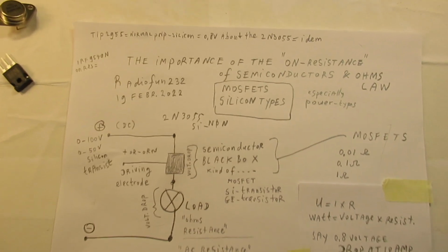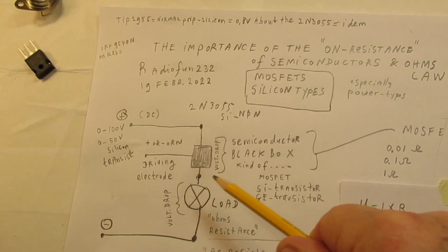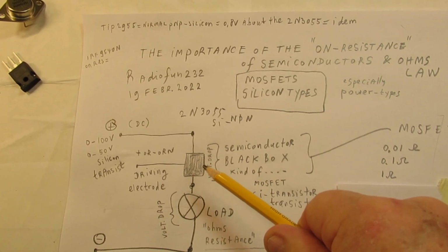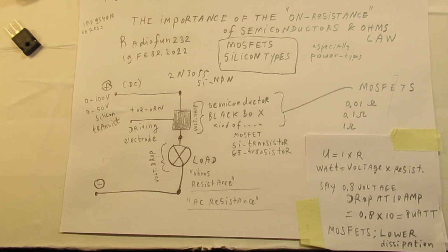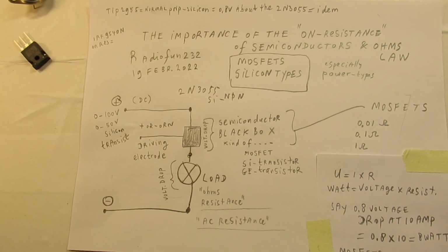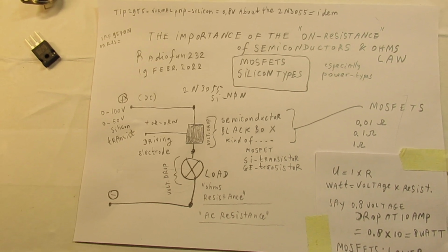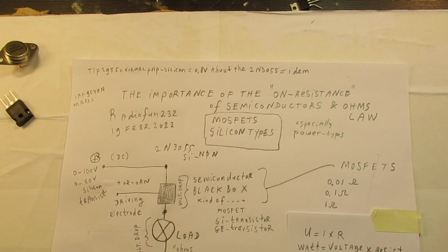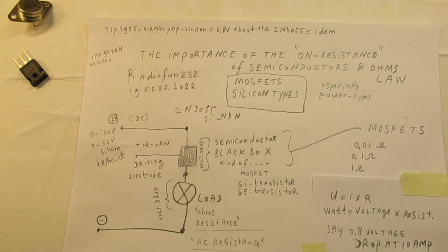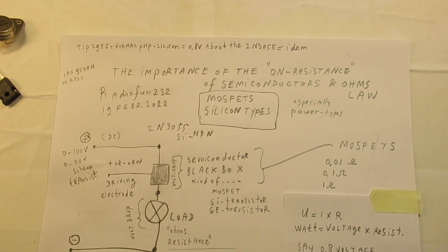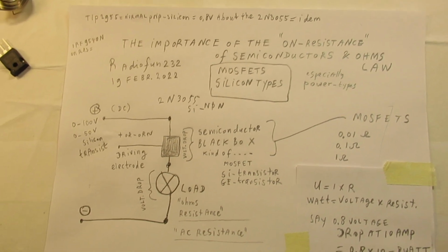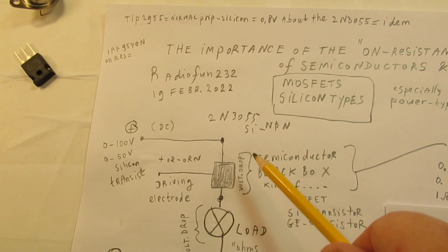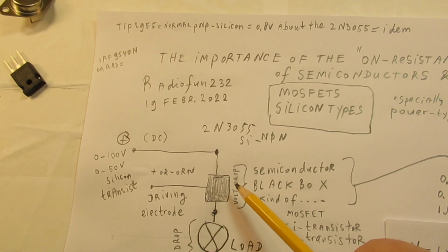That's important, of course. There's always a voltage drop here in the range between, say, 0.1 or even 0.01 volt and approximately 0.8 volts. And 0.8 volt is directly related to the silicon transistor because of its physical properties. So with a silicon transistor, when it's driven into saturation, there's a 0.8 volt drop.